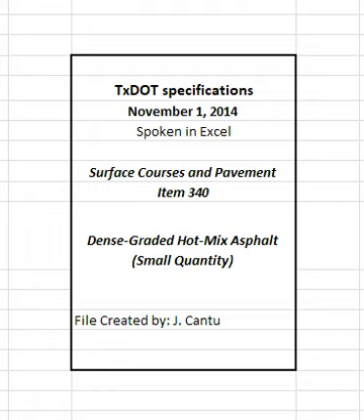4.6.2 Tack coat. Clean the surface before placing the tack coat. The engineer will set the rate between 0.04 and 0.10 gal of residual asphalt per square yard of surface area. Apply a uniform tack coat at the specified rate unless otherwise directed. Apply the tack coat in a uniform manner to avoid streaks and other irregular patterns.